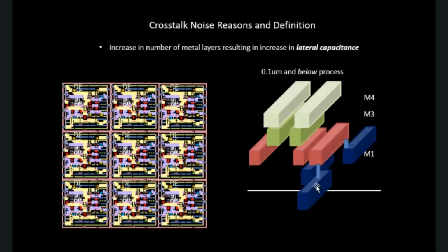if you see, initially the metal one was directly connected, it was a straight line. But now what we are doing is we are taking the metal one, we are stopping over here, we are taking one connection on the next metal layer, which is, let's say, metal 2. We are continuing with the connection, we're again coming back down to metal 1, and then we're continuing with this connection. So now the signal which was traveling this way, it will now travel this way.